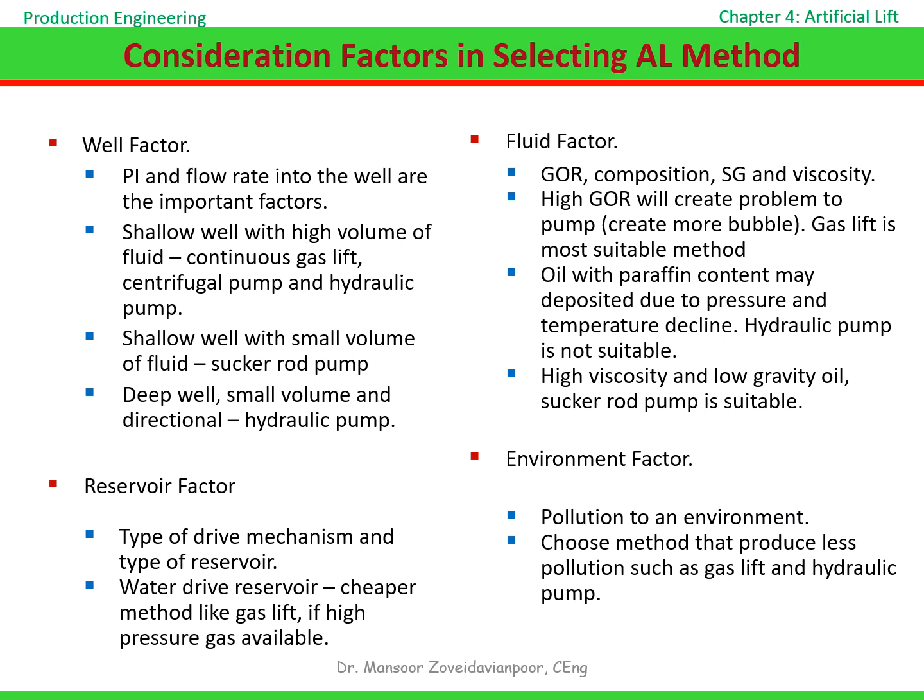High-rate wells often favor systems such as continuous gas lift, ESPs, or hydraulic pumps. On the other hand, shallow wells producing smaller volumes may be better suited to sucker rod pumps. For deep directional wells, hydraulic systems are often considered because of their operational flexibility.